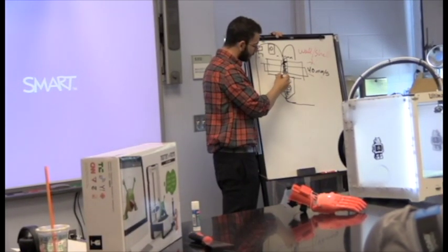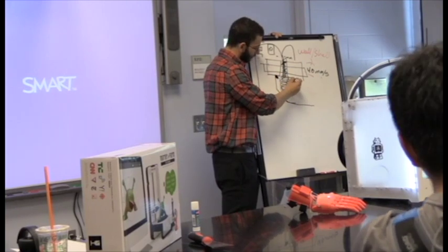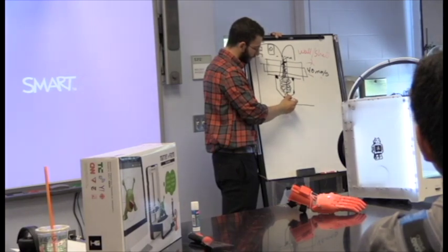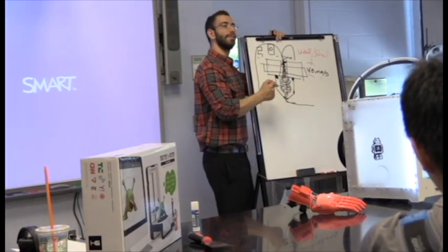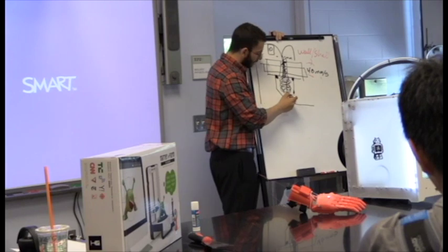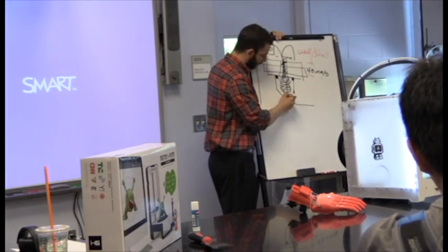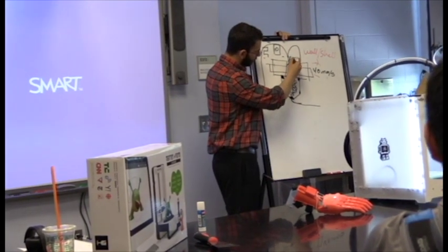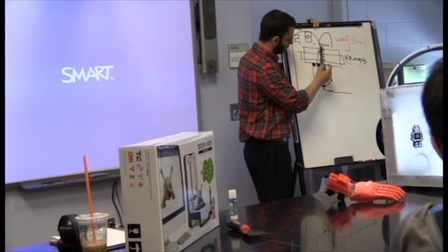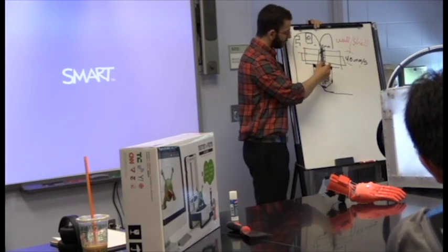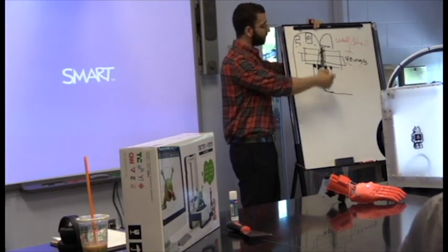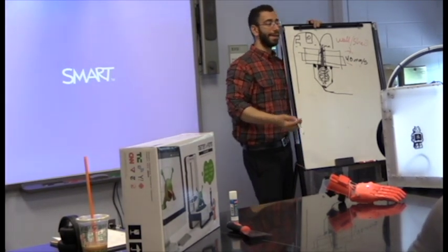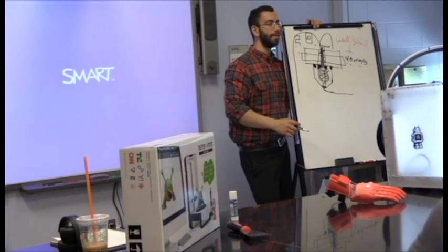However, sometimes stuff gets to these corners, right? Where it's not very hot. So sometimes in these little corners, it solidifies and gets stuck. And it's enough to sometimes completely block the filament from going through. Usually not down here, it's usually up here. It builds this little wall and stops the filament from going through. And that's called a clog. And that's very common, it will happen a lot.